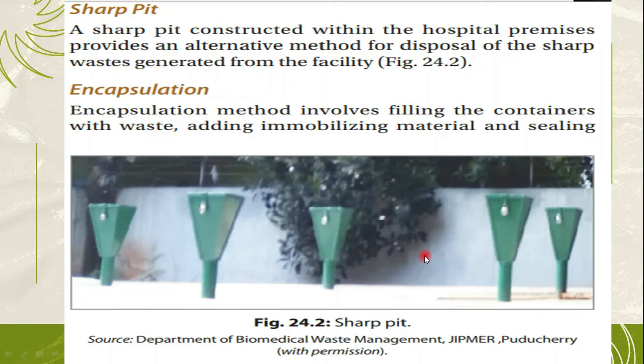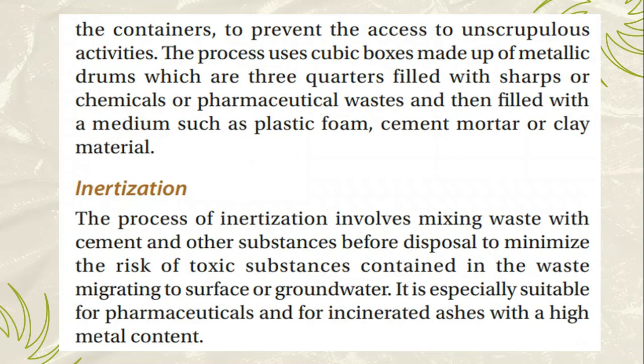Encapsulation: encapsulation methods involve filling the container with waste, adding immobilizing material, and sealing the containers to prevent access to unscrupulous activities. The process uses cubic boxes made up of metallic drums, which are three-quarters filled with sharps or chemicals or pharmaceutical waste, and then filled with a medium such as plastic foam, cement mortar, or clay material.